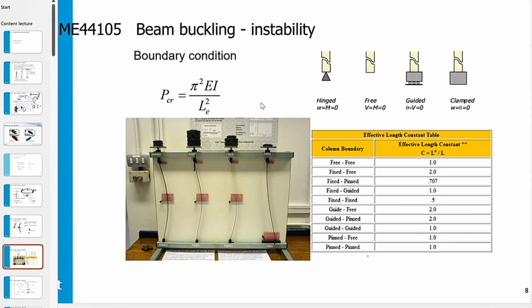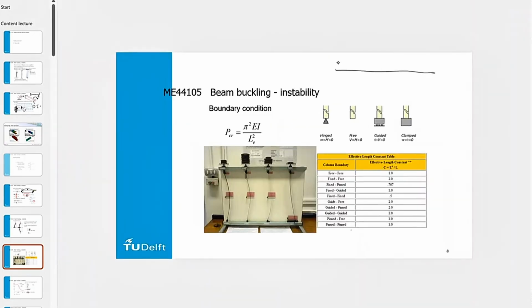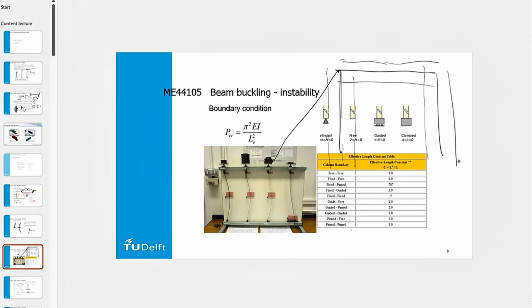For example, if I have a beam model where I have a connection here and a connection here, and then I don't know, this continues, something like that. If you want to take a simple modification, is for example, if the beam shapes are considerable, then you could say, okay, this is the buckling length in my beam model, but in reality it is supported here and there because these beams have a certain size, so that you can easily modify that buckling length to between these edges.